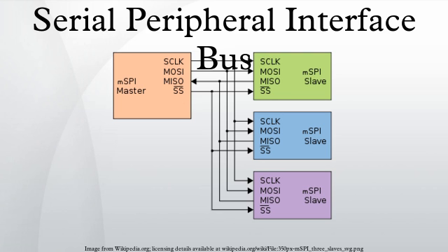Oscilloscopes: every major oscilloscope vendor offers oscilloscope-based triggering and protocol decoding for SPI. Most support 2, 3, and 4-wire SPI. The triggering and decoding capability is typically offered as an optional extra. SPI signals can be accessed via analog oscilloscope channels or with digital MSO channels.